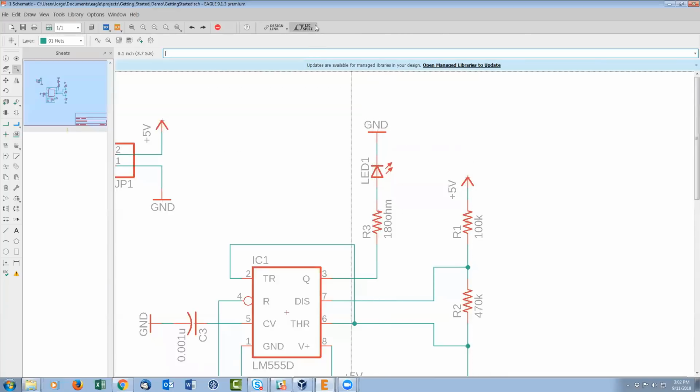Right now, what you will do is left click here, and you'll get this menu. The first thing you have to do is click Export Setup. That'll make sure that the ULP is aware of where your LTSpice installation is. It'll check that it has corresponding libraries, etc. If everything pans out, at the end it will tell you what those directories are. Then you can go import and so on and so forth.